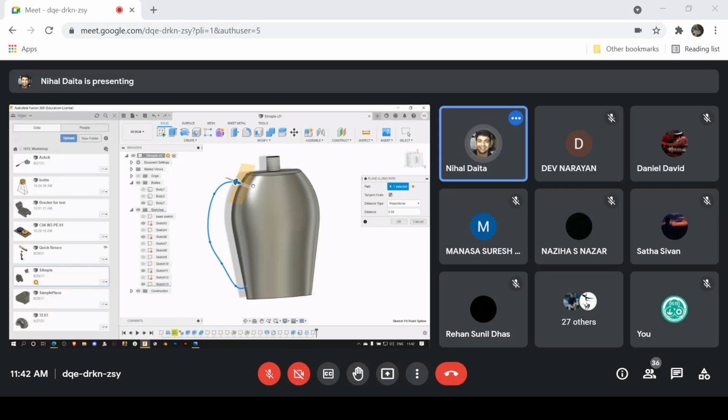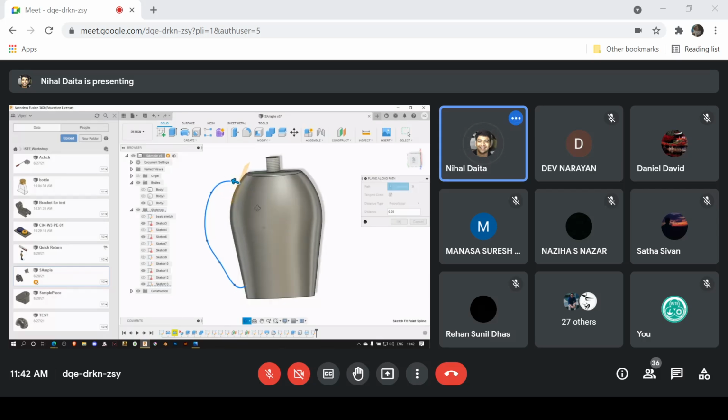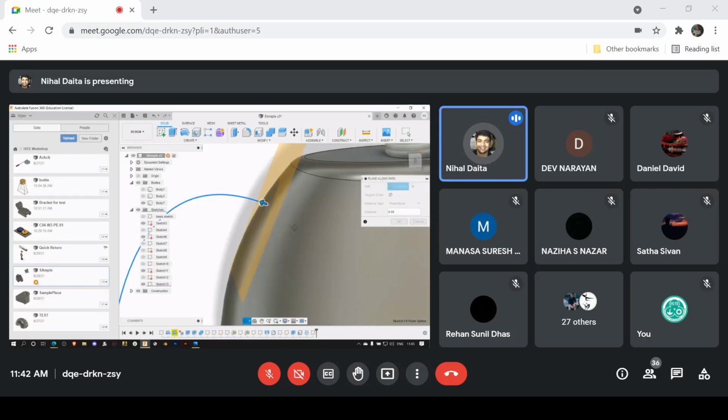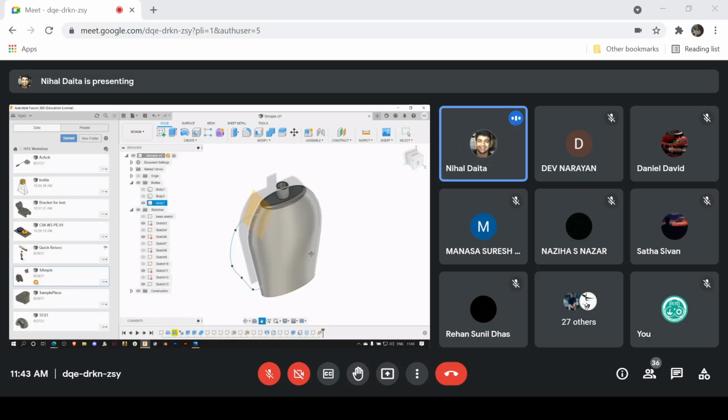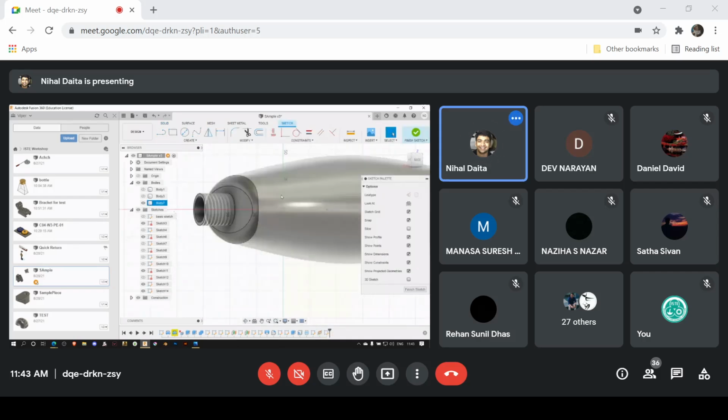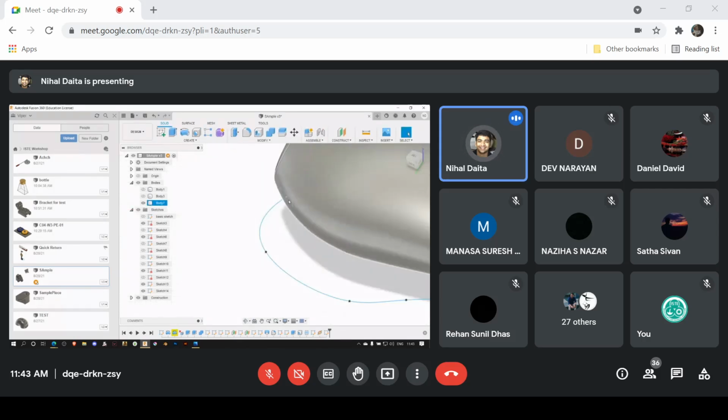I'll just keep it at the end because I have to extrude the entire thing. It's good that it's inset a bit, so the end doesn't show out. I just click OK, and my computer has hung up. It's back. And if I just create that plane, right, I create a sketch. I just give it a rectangular frame for now. My objective is to use this rectangle and drag it along the path.